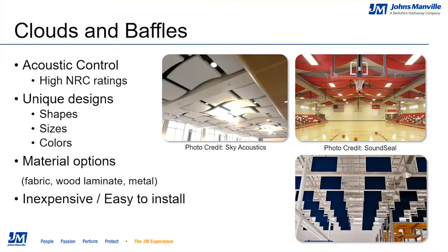This gets confusing with the different sizes and shapes of baffle and cloud designs. Technical product literature from manufacturers, or in some cases working with an acoustical consultant, can help with the recommended number of baffles or clouds and the appropriate spacing. As with acoustical wall panels, baffles and clouds are an inexpensive way to improve both the sound control and aesthetics of a space.